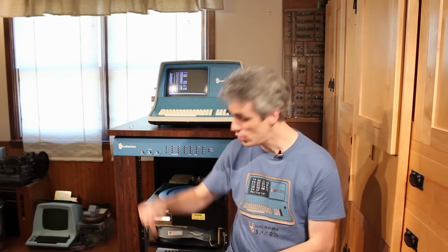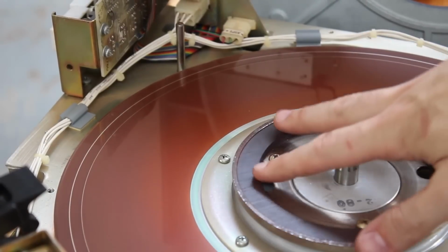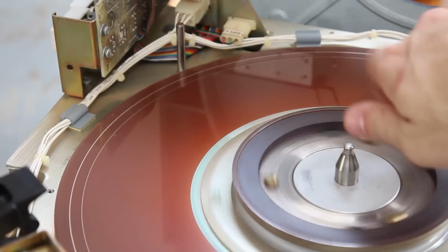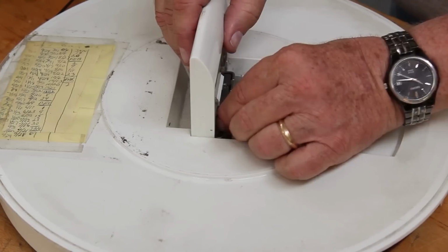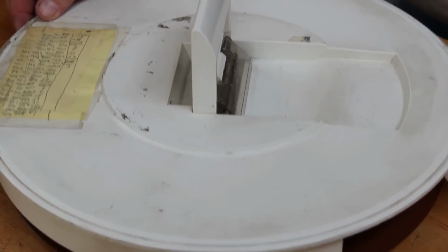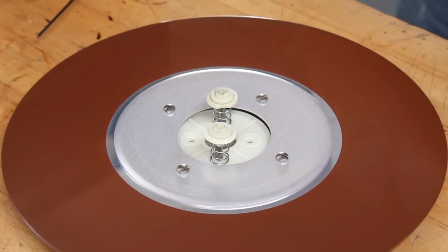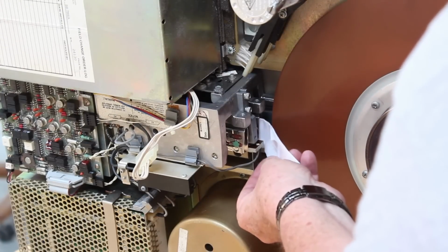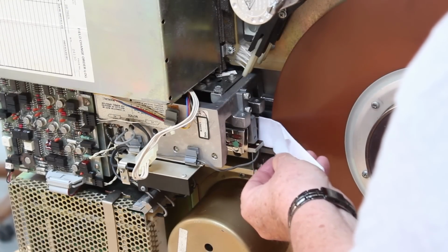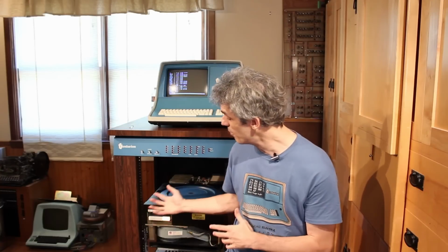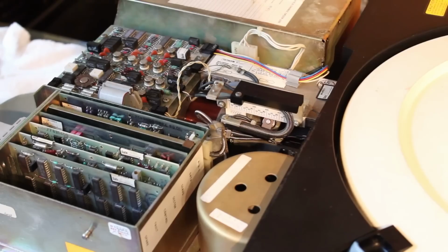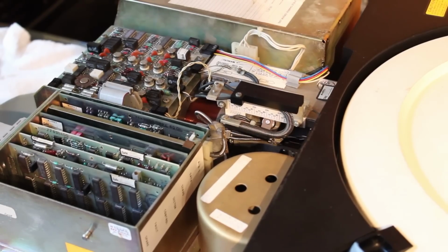Also, we have another complete Centurion system to build. And I think using this Hawk drive as a working drive, we can actually repair the drive that we crashed. I can pull the crashed platter out, sacrifice one of our removable platters that just has boring accounting data on it, put that as the new fixed platter in that drive, clean it up, spin it up, and then copy the contents from the removable platter that has the operating system on it onto the fixed platter, and then we will have 2 fully functioning Hawk drives.